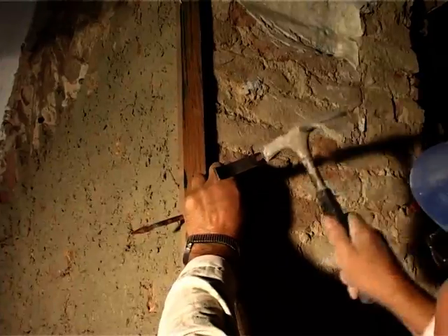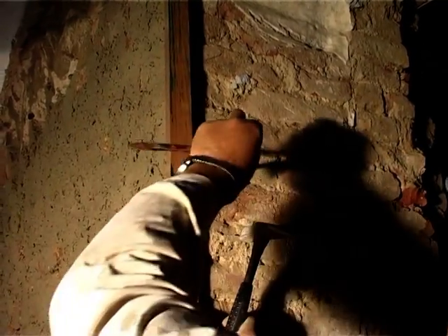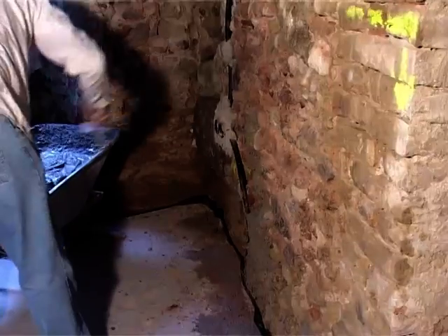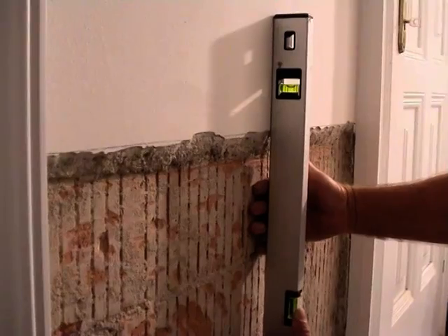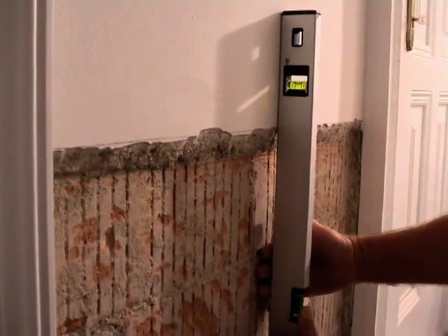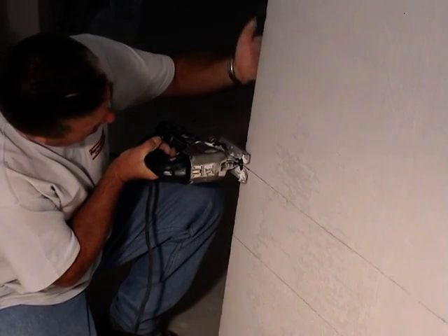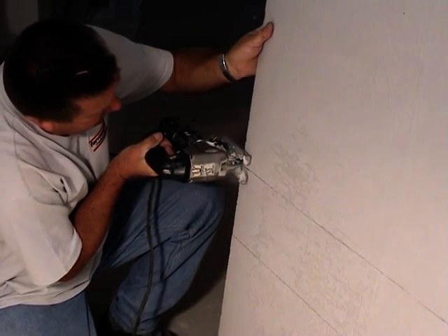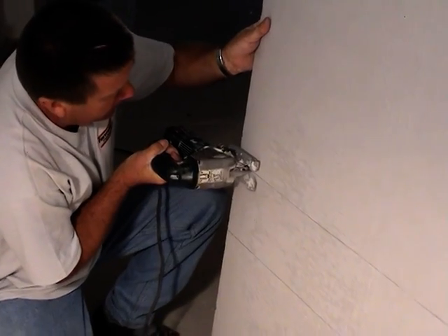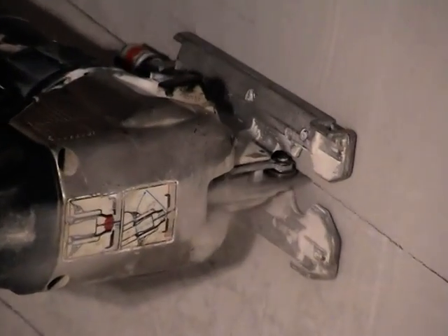If the wall merely needs a new coat of paint, it should be painted after the evaporation phase. According to the ÖNorm, Austrian standard, and according to our long years of practical experience, the actual plaster renovation should be performed only after the wall has been dried. One thus avoids migration of the salts into the new plaster and consequent undesirable chemical reaction.